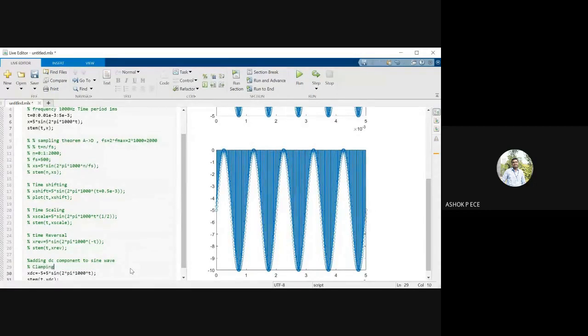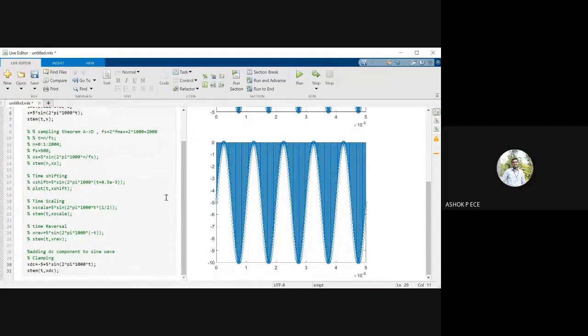So all the television signals are composite, the TV signal is called a composite, right? So there we usually clamp and send. So when you clamp it, the signal will be moving upwards or downwards from the reference x-axis. At the receiver end, they will use clamping as a reference signal to extract the original signal. See, the original signal is sine wave, but what is added? It is clamped to plus or minus 5. So when you remove this clamp, you will get back my original signal.